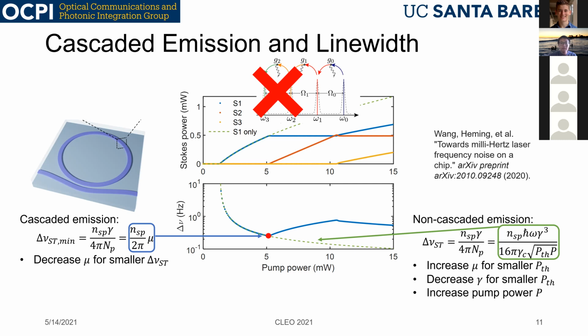So first question, you ask, is the fabrication done in UCSB? If I remember correctly, the process till the etching of the silicon nitride was done at UCSB, and then we sent it out to our collaborator at Honeywell for this thin layer of silicon nitride film deposition and upper cladding deposition, because they have this TEOS PECVD tool, which could give us a better loss performance.